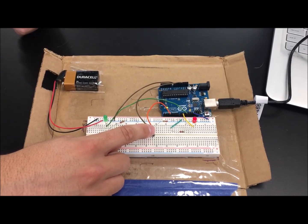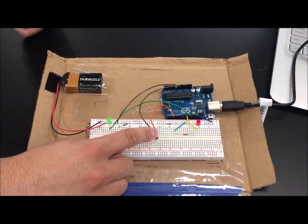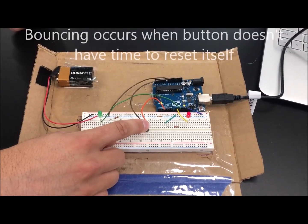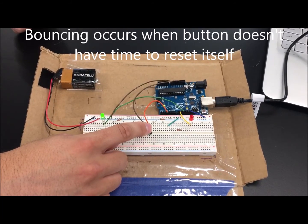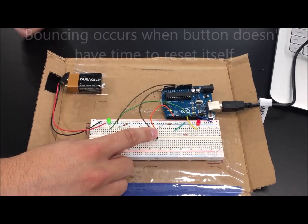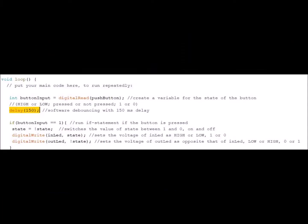One issue we faced in our initial program occurred when we pressed the button and the LEDs didn't alternate properly, and sort of flicked between each other. This problem is formally known as bouncing. Bouncing can occur when the button essentially doesn't have time to reset itself. This can lead to an error when pressing the button. To fix this, we inserted a 150 millisecond delay.